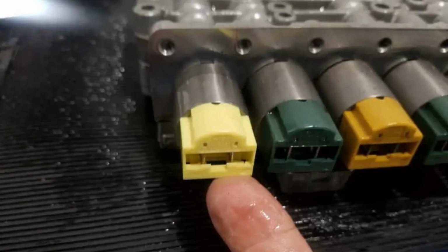more difficult. To correctly change the mode of operation, based on the functional purpose of the used solenoids of automatic transmissions, another classification is distinguished. LPC or EPC solenoids. Control devices that go one of the first on the hydraulic plate. This solenoid valve is the key or main valve. It independently distributes oil to the other working solenoids and oil channels. If a four-stage EPC is used, the control solenoid is usually always the first to wear out.